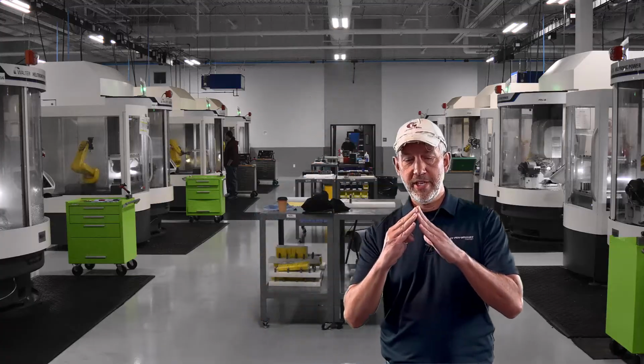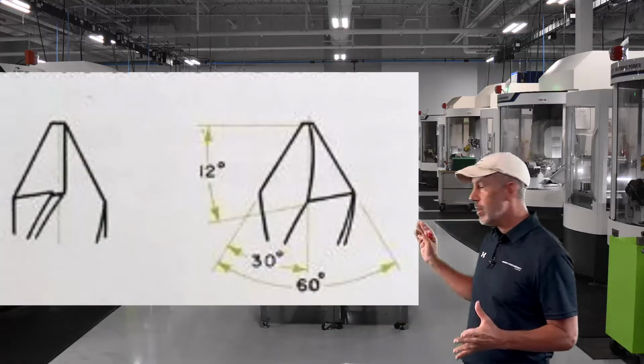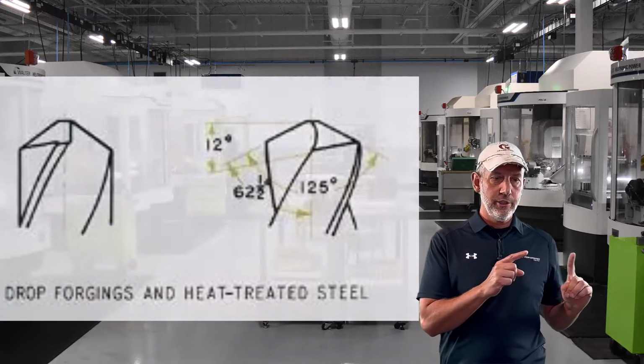So let's look at a couple of point angles, okay? The main thing I want you to understand about a point angle is the steeper the point, and when I say steeper, it looks like more of a pinch to it, the softer the material. The flatter the point, the harder the material that you're going to drill.